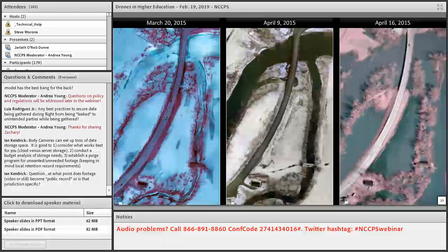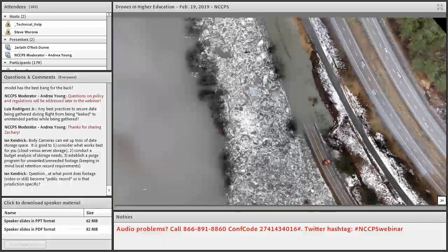So here we're tracking flooding using color infrared imagery. This is just light that's a little bit beyond the portion of the electromagnetic spectrum, and we're looking at it in March, April, and then mid-April. So you can see where we go from ice-out conditions to flood conditions. So if we want to re-engineer our roads, we've got very, very good data at peak flood conditions to show where the flood happens. We can also use it to document the flood conditions themselves for a specific incident.